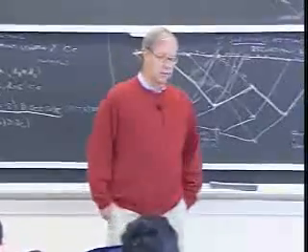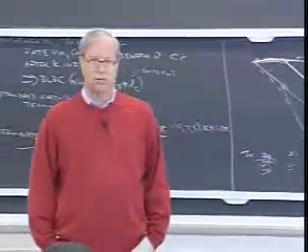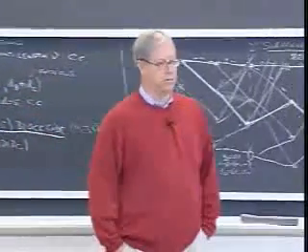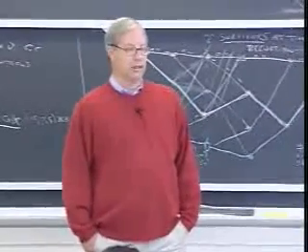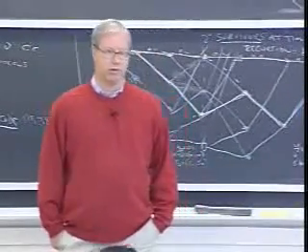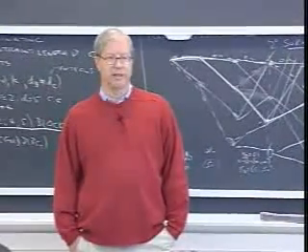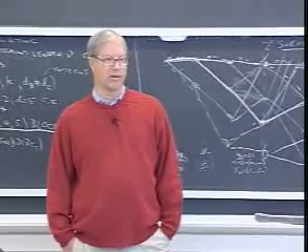I've already mentioned that around '90 they went up to this 2 to the 14th state Viterbi decoder. They went to much more powerful outer codes, much cleverer, and they were able to get to within about 2 or 3 dB of the Shannon limit. And that was the state of the art on the eve of the discovery of turbo codes, which is where we're going in all of this.